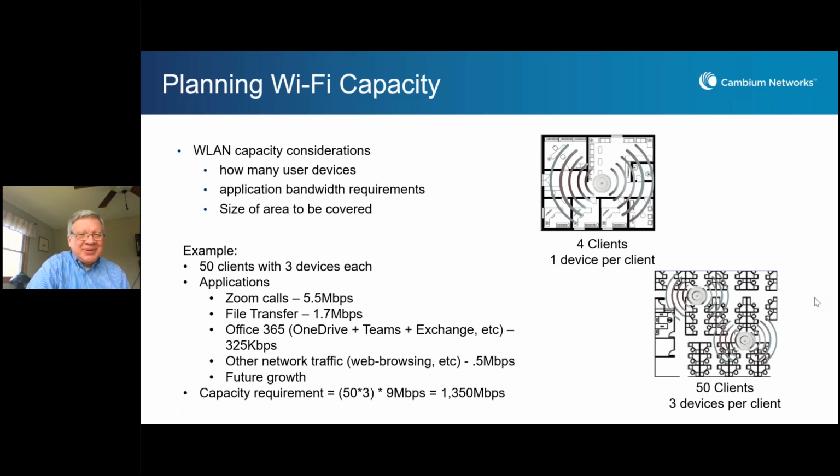And another tip here from Adam, who says that when doing your survey, make sure that the switch providing the PoE is also 48 to 52 volt DC and not just 24 volt. Oh, good point. Yes, thank you. That's something I tend to not even think about, but that's a very good point, Adam.